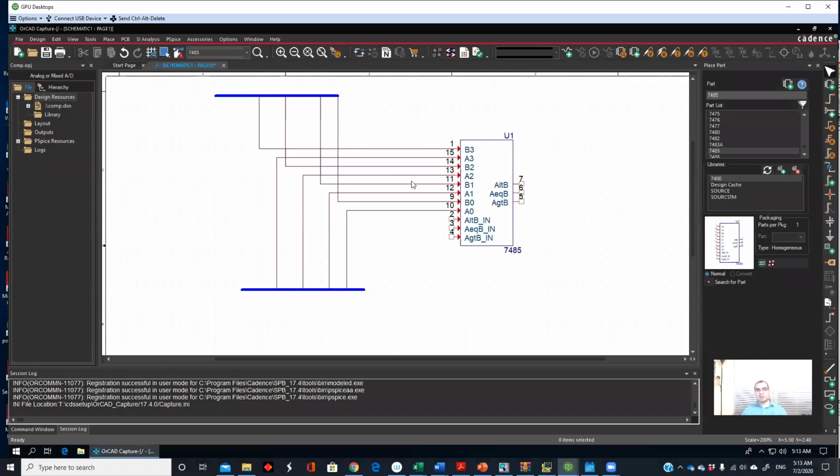All right, so now we are done with wiring B and A. And what you have to make sure is there is no connection between, of course, the wires A and B. So here they are not connected. If you see a solid node here, it means they are connected. So just make sure that there is no connection between the different wires we have here.